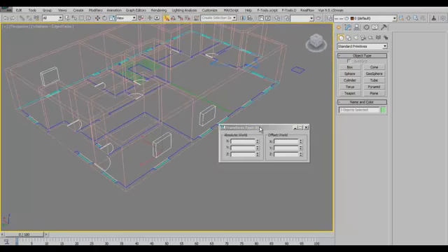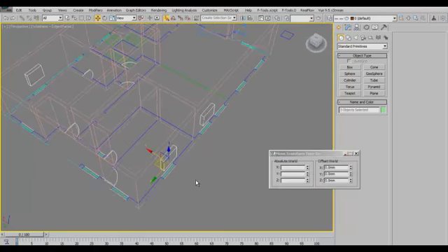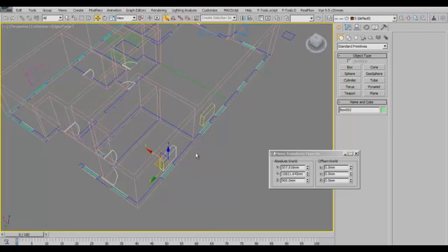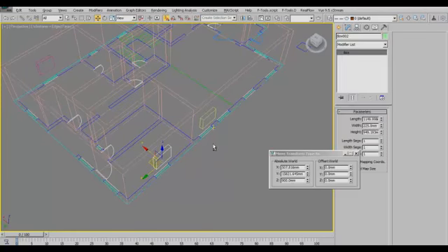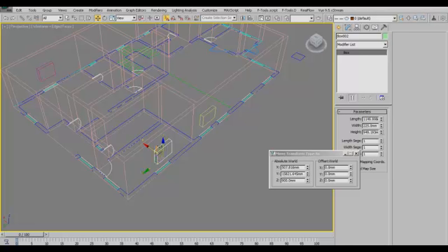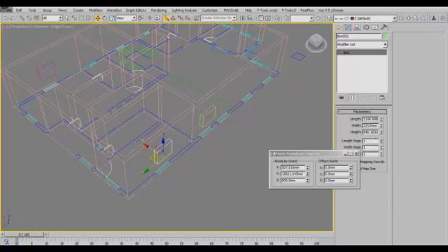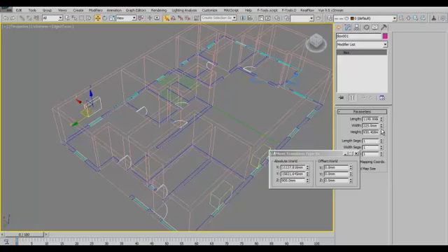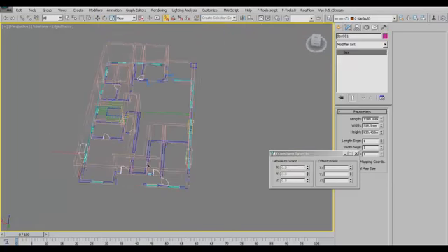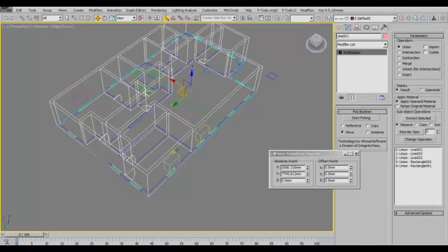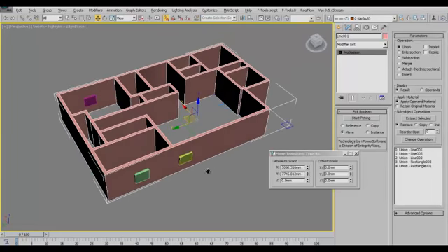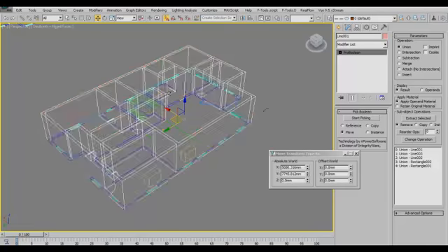Then one other thing I would always advise you do, so you don't get errors in your booleaning, you would need to make the width of this particular thing just a little bit higher than the original width of the wall, which originally is 225, but we just increase it slightly. It doesn't matter how much you increase it, but it should just get a little above it, and that is what we need. So now let's go to our shaded mode by using F3 as my shortcut.